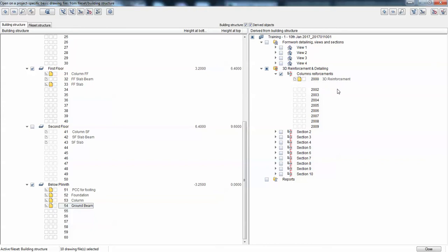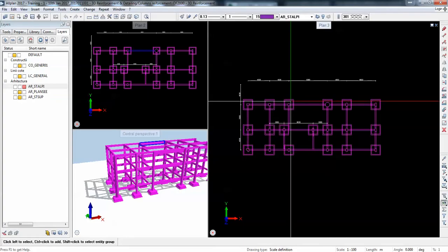This is required especially for big projects, as the program will create some linking between the drawing files, and if the linking is not done accordingly, we have drawings that contain reinforcement, architecture elements and also associative views, we can get a lag of the system and the program might run slowly. So this is one solution. Of course, for creating reinforcement, we will need associative views, but after we create them, we either delete them or move them to the detailing drawing.